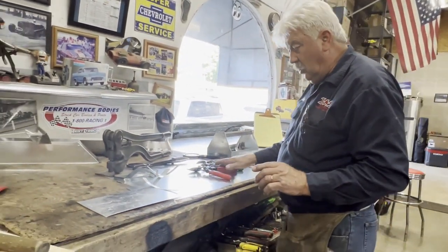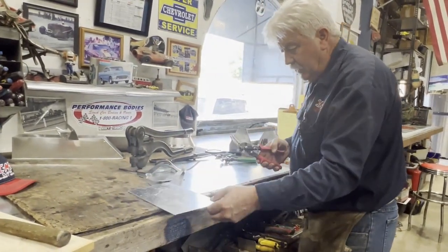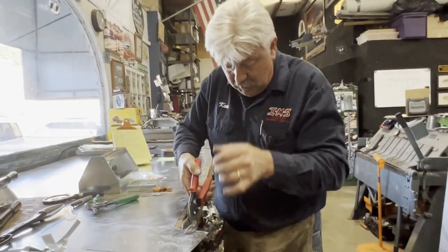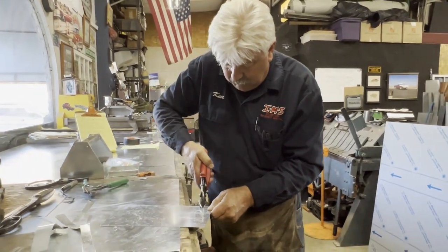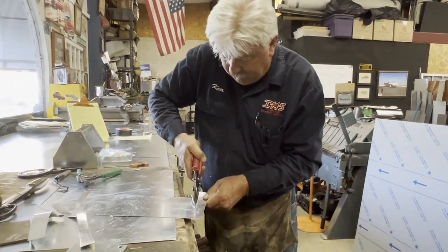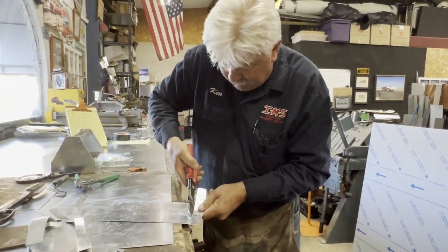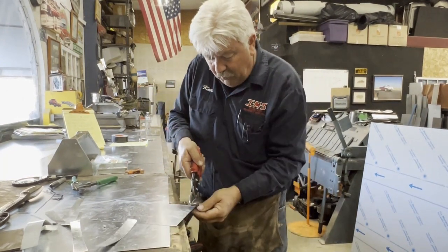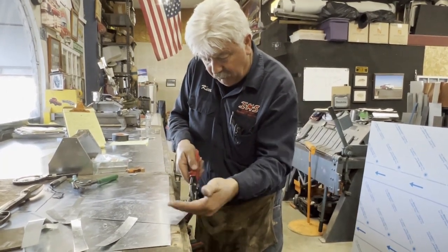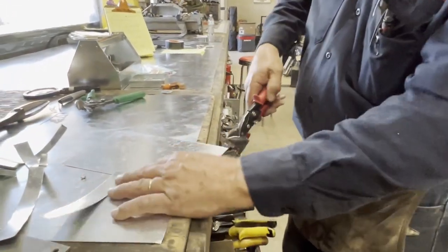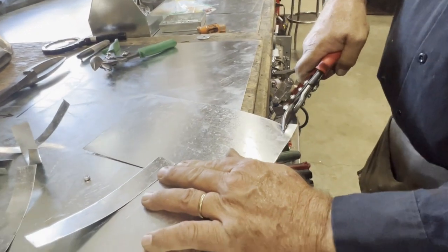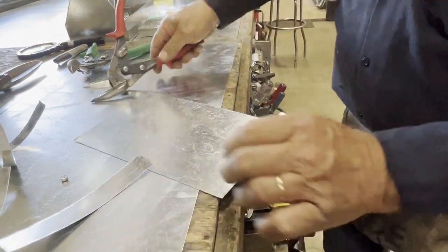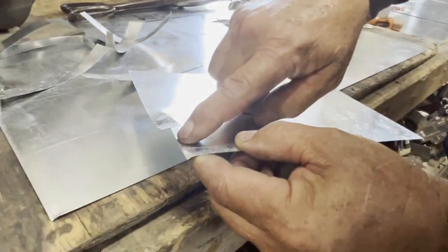One of the things that I want you to always remember is while you're cutting, always hold the snip perpendicular to the work. What we want to do is I want to cut perpendicular. So see, with my left hand, I'm spreading. With the right hand, I'm shearing, spreading and shearing. What I want to do is always hold the snip perpendicular to the work. If I find myself cutting at a different angle, you're going to find your snip will make it very difficult on you. What it wants to do is it wants to roll up an edge.